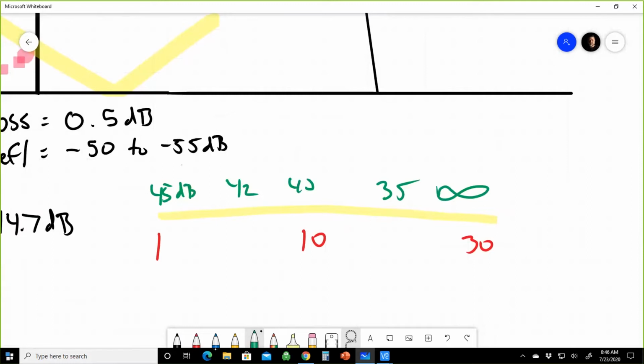The main reason why is because the glass is getting so long that if there is reflection here from the glass, it's too weak to come back. And that's what we need for reflection. So fiber contributes only so much ORL. Then eventually it just flattens and it remains that number until infinity. And it's somewhere in the mid-30s to high 30s. I'll have to look it up, and in the follow-up email, I'll find that chart and send it to you. That way you have something more accurate than my conceptual drawing here.